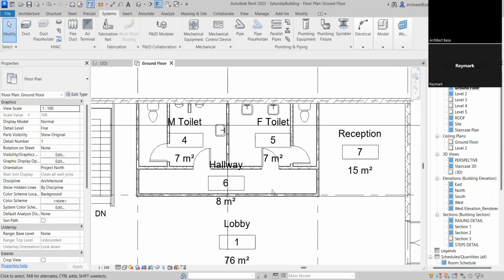The mechanical model is usually the HVAC model. So when we're talking about MEP, in Revit, M is usually for HVAC, and then P is for drainage and water supply. And then, of course, E is for electrical. Under electrical, we have so many elements like fire alarm, power, lighting, even the low voltage are included. Security is usually included in the electrical model. And then F, firefighting, is usually a separate model, even if these are just pipes.